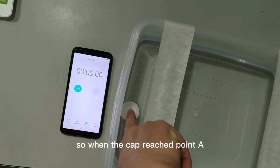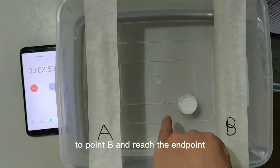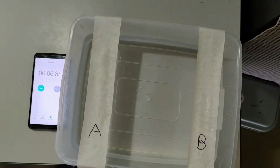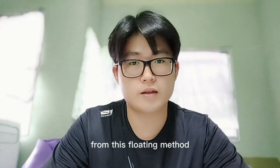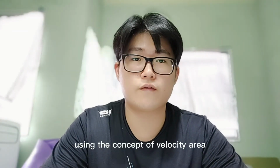So when the cap reaches point A, we start the stopwatch, and when it flows to point B and reaches the end point, we immediately stop the stopwatch. Okay, so this process we need to repeat three times to obtain the average value. So from all the data we measured from this floating method, we can calculate the value of stream flow discharge using the concept of velocity area.